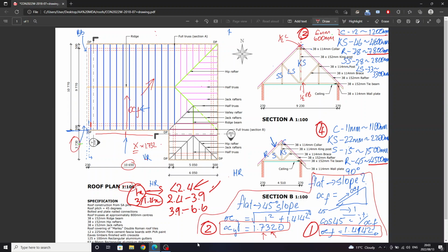So what I did was I just assumed it was, I think it's 345 again. And I said, well, 345 will fit into the 500. And remember, it's 345 on slope, so you actually have to consider that it's a bit shorter because it's on slope. So it definitely fits in. So what you'll say logically is that you can fit 2. And those 2, the first one would be your tilting fillet, and the second one would be your batten.